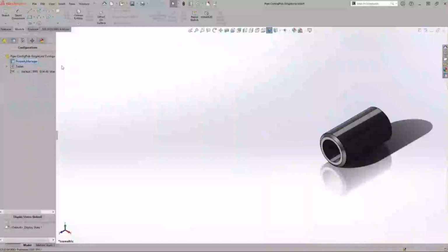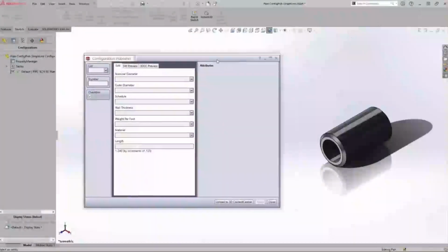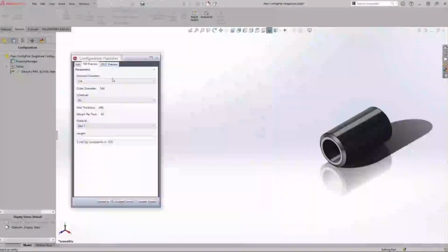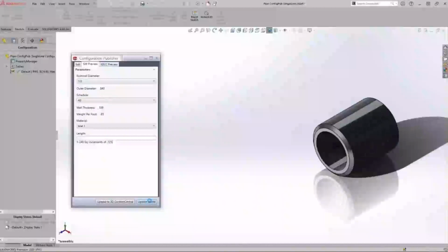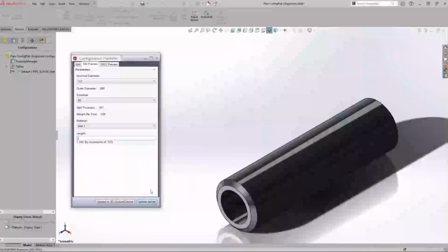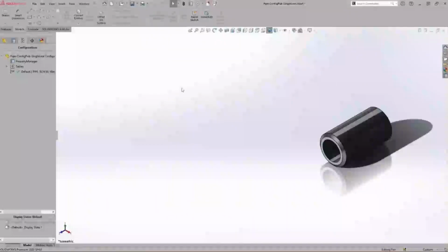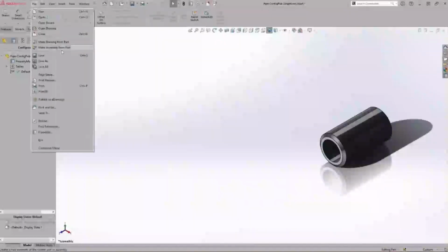We'll edit the feature of the property manager. That's what it gets called. It'll load up the design table. Don't be surprised if there's a little refresh issue. And then we can go to the SolidWorks preview tab and see how it works. So this is that testing process that I mentioned earlier. The one area where we're letting the end user key in a value is the length. So we could specify different diameters, different schedules, different lengths. But notice there's only one configuration in the property manager.